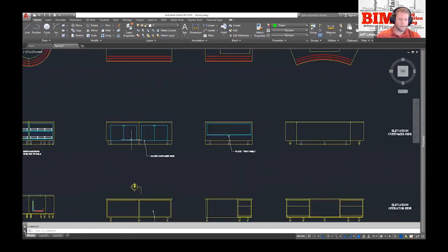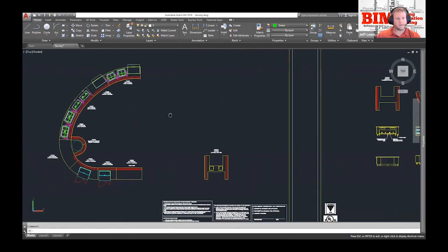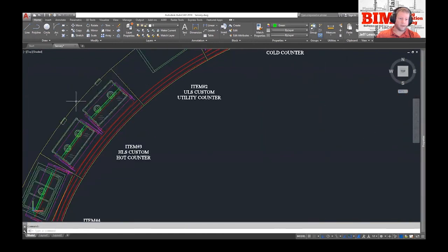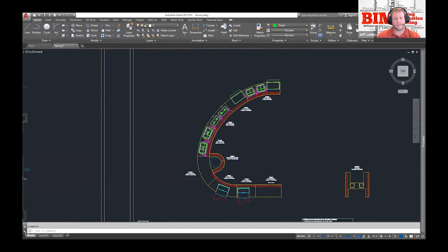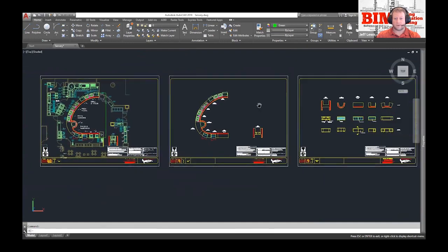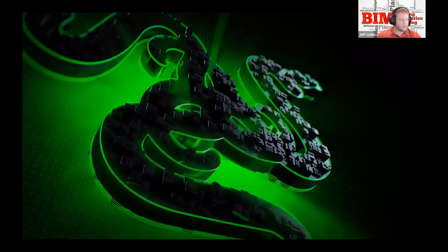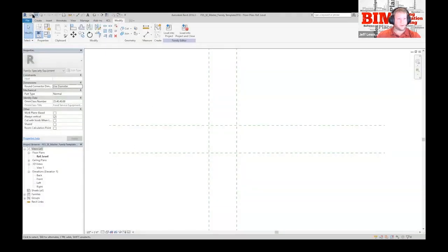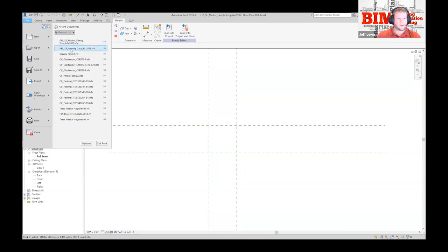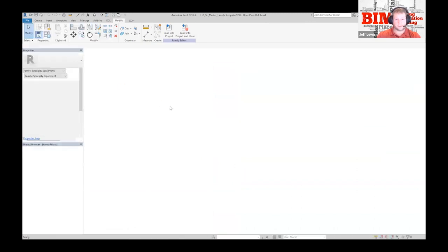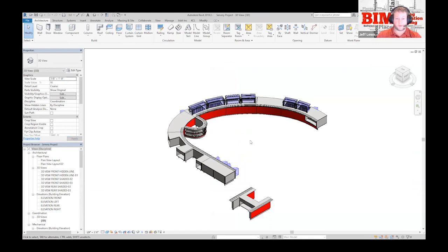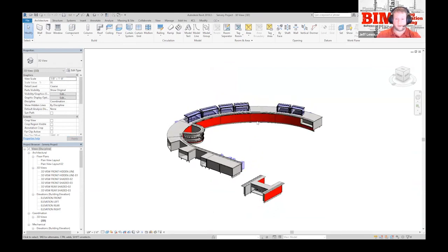In the plan of attack, from top to bottom, as you see in the back, that may be curved, but being supplied good drawings, we found out they are actually straight in the back but curved up front. So it's always good to spend your time on the plan of attack before even going into a REVIT file. What I'm going to show you is the created project, and instead of drawing from scratch, from the bottom up and taking all that time, I'm going to do what's called a reverse engineer.